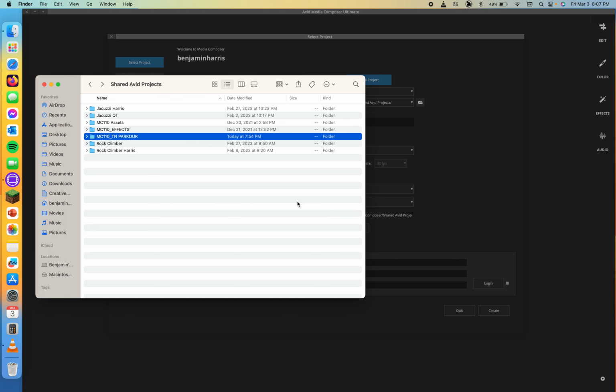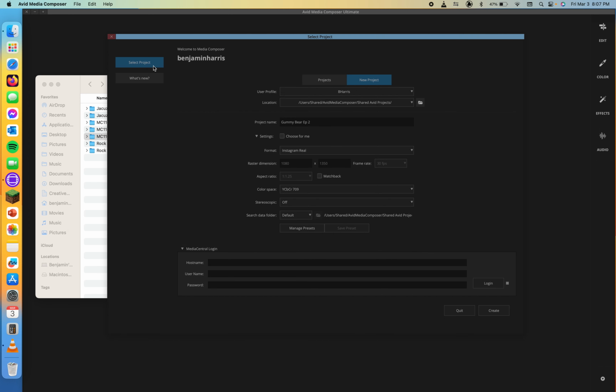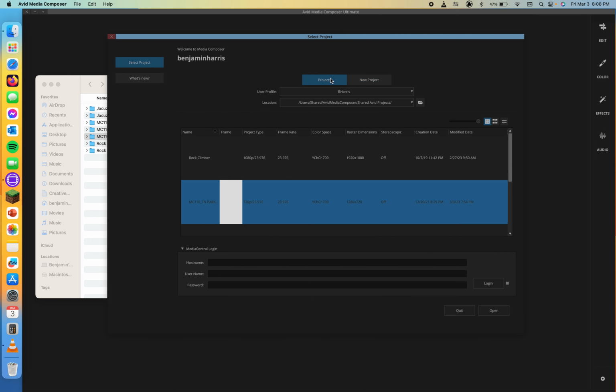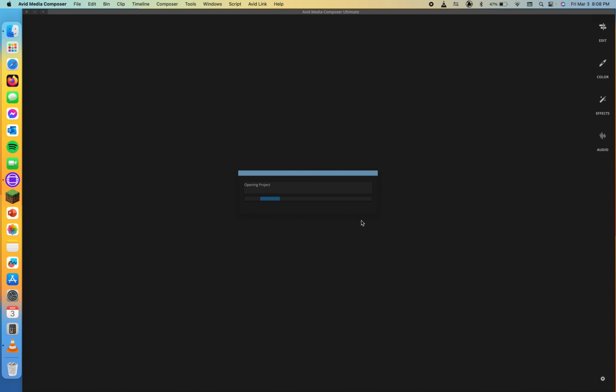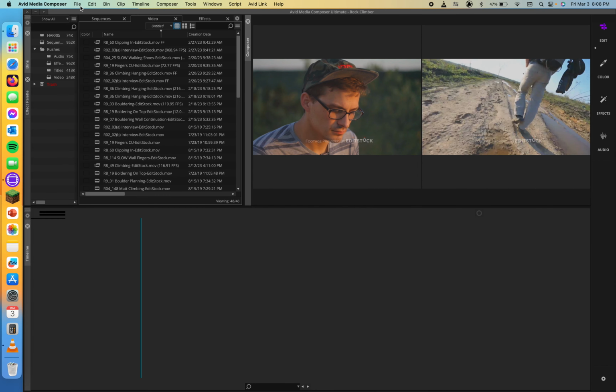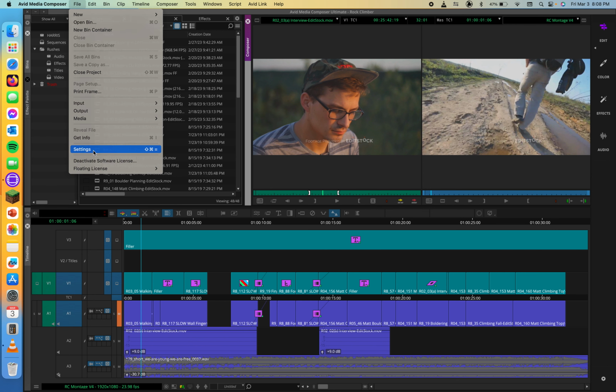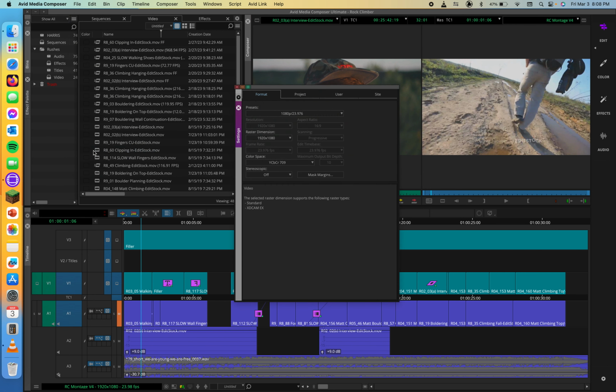All right, setting up a project. So after you create a project, we can change its format if needed. So let's exit out of this. We'll go to the project window. We'll open one of these. We'll go to Rock Climber. Let's destroy Rock Climber. Why not? So if we want to change the project format, we can go to File, and then Settings, and here we're going to ensure that the Format tab is active.